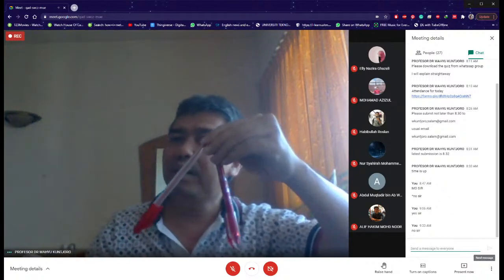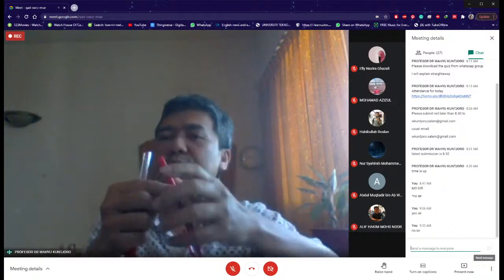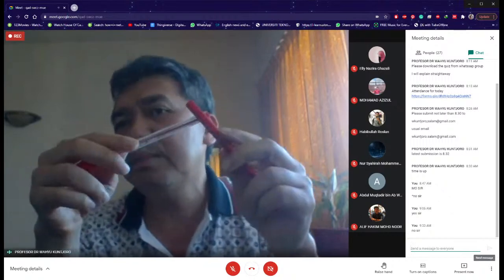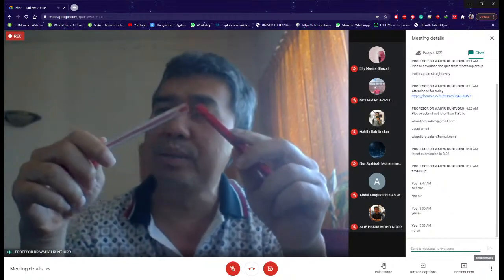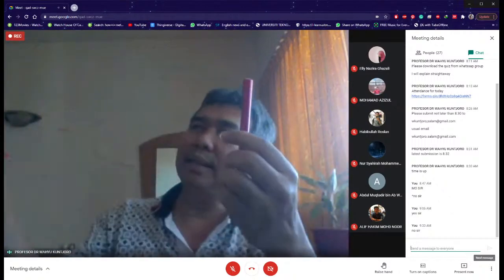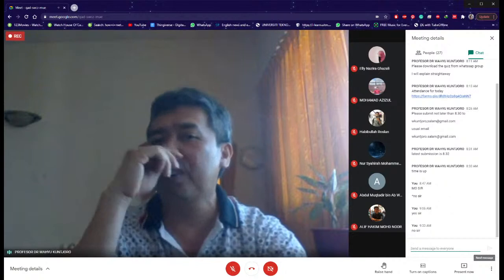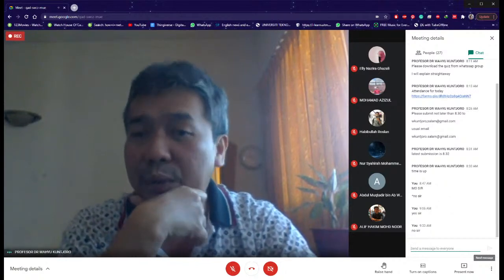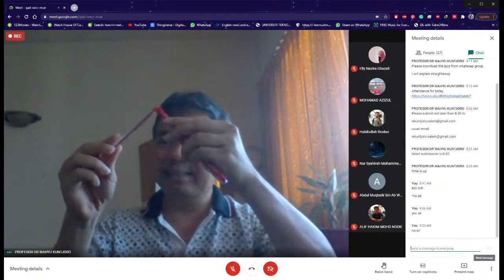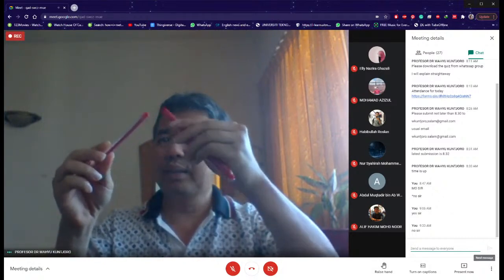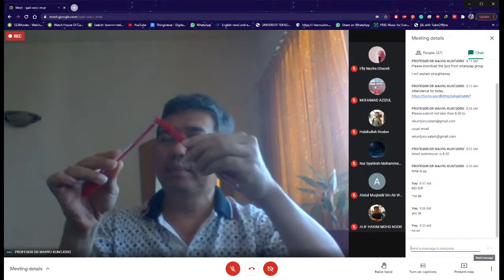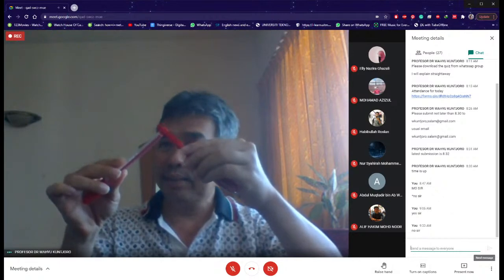Because now we have also moment. And if it is welding at the junction, then of course, potentially you will have bending moment over there. So if you have moment, force in X, force in Y, then of course you are talking frame. Now, what about if this is also welding? All right, so it is a frame.